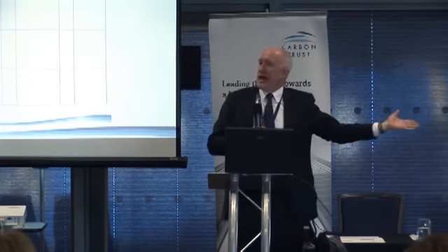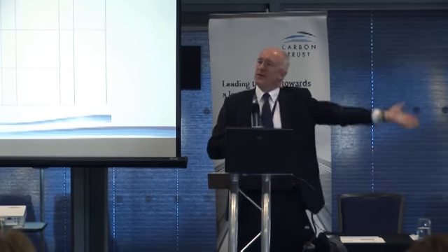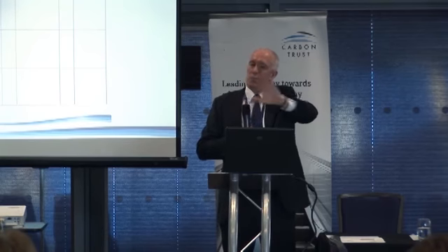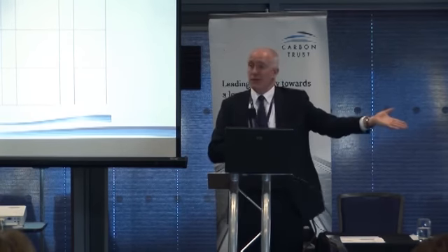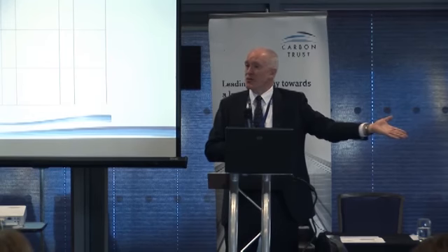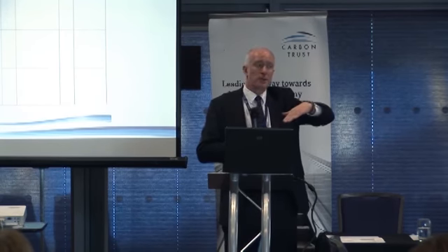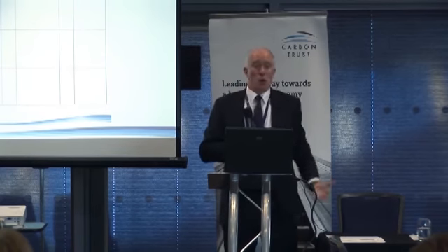We're not going to be able to get any heat recovery from 35 up to 71, 82. It's not there. So the fact it's by the boiler house is not helpful. But what's in the boiler house where we might be able to get some heat recovery at 35? What could we usefully use 35 degrees centigrade energy at in the boiler house? Any thoughts? Hot water. Domestic hot water preheat.